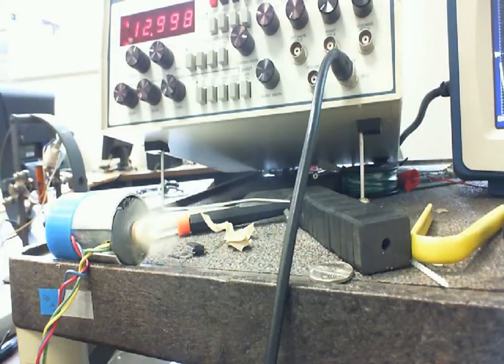So the span would be the full range, right? You understand that? Then we'll set up a span. We'll hook it up between two resistors and actually get a span. Normally with a pot, if we hooked it up to 10 volts, we would go from 10 volts down to 0 volts. But I might not want to go from 10 volts down to 0 volts. I might want to go from 5 volts to 3 volts, right? You understand that? So we have the ability to show you how we can set the span on those things.